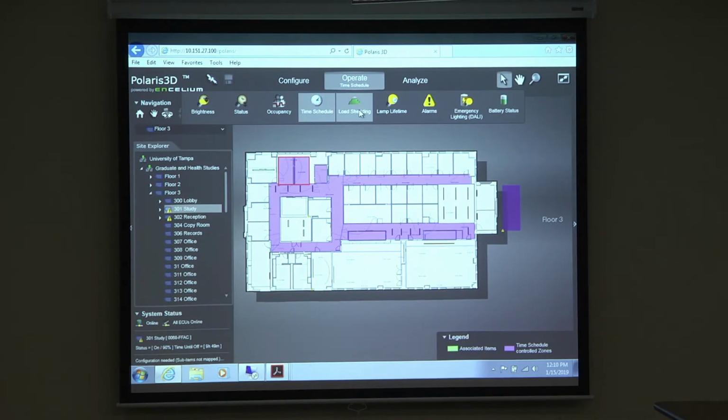For example, say you require 50 foot-candles in a room. When there's no sun outside, you set up the room for 50 foot-candles. You put your light meter on the table and adjust light levels to satisfy 50 foot-candles in that space.